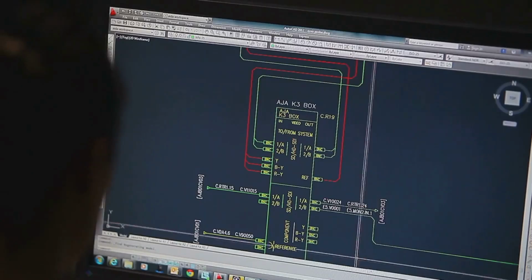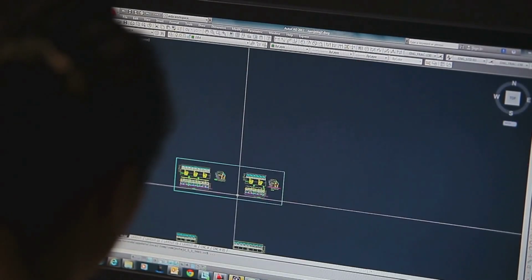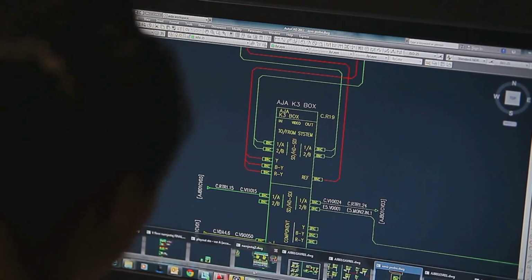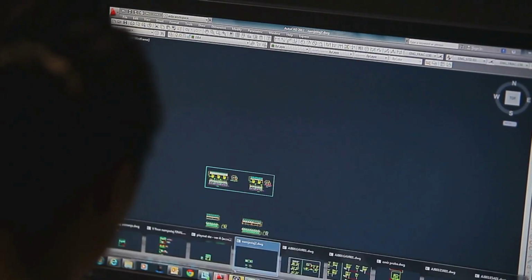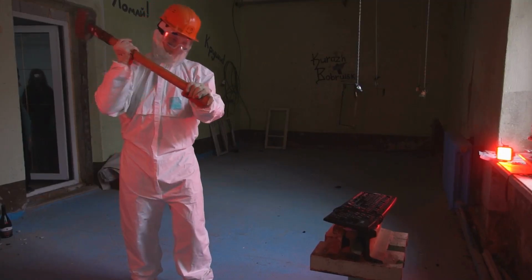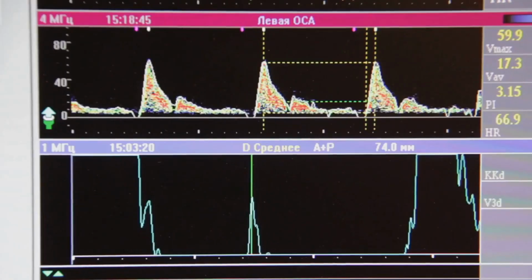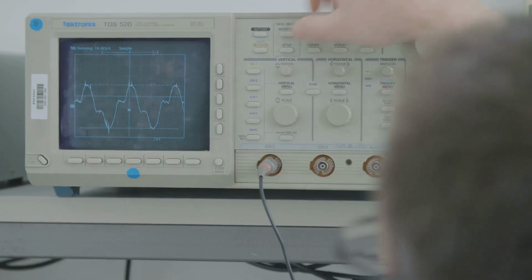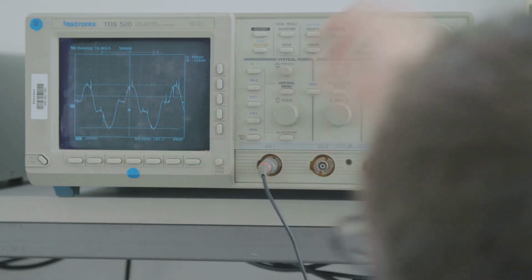Now it's time to pick the right tool for the job. CST Studio Suite offers a whole arsenal of solvers, each with its own strengths and weaknesses. For radiated EMI, we're mainly interested in the time domain solver or the frequency domain solver. The time domain solver is like a sledgehammer. It's great for analyzing transient effects in wideband emissions. It's like hitting your circuit with a short, sharp pulse and seeing what comes out the other end.